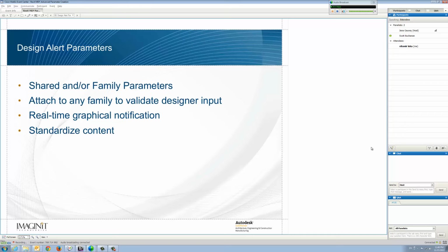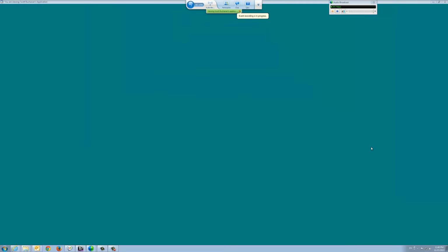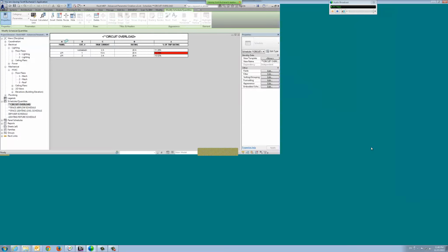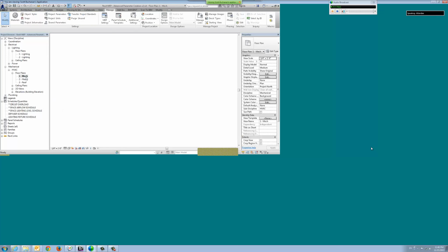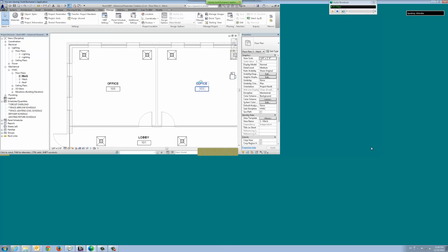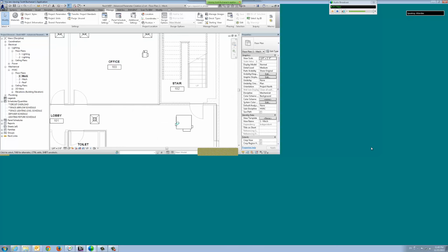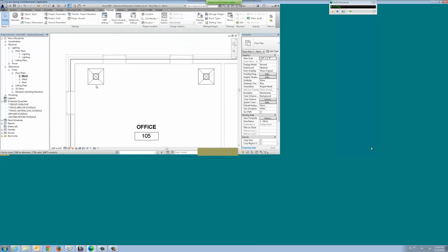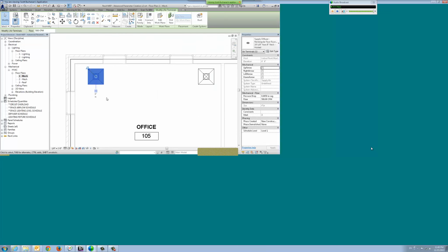So again, coming back over to our project, within diffusers, again, I can do it. There's that VAV, that's that one there. I have the electrical connector, so there's our unassigned circuit. So on this diffuser, once I select on it, the default diffusers come in with an airflow of 500 CFM. So if you haven't touched them in the software, that's what they're going to come in as.